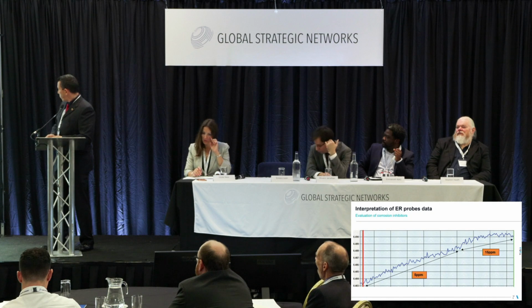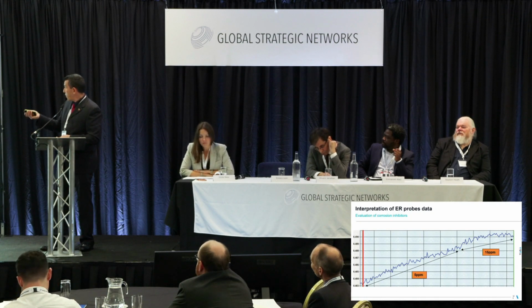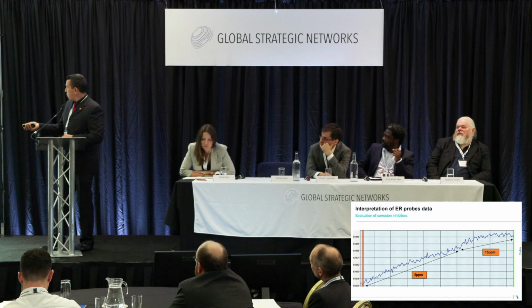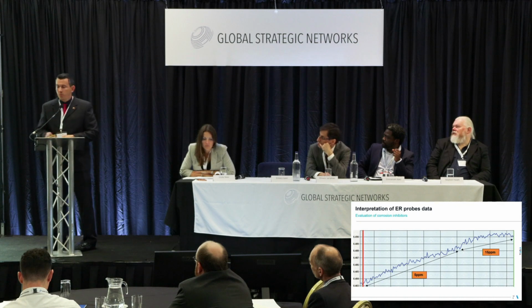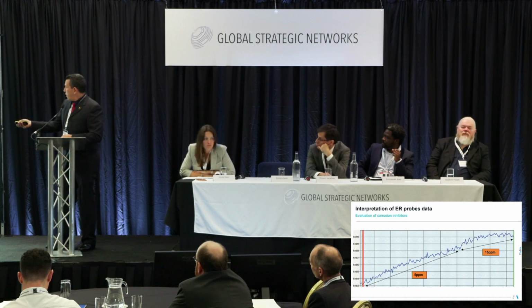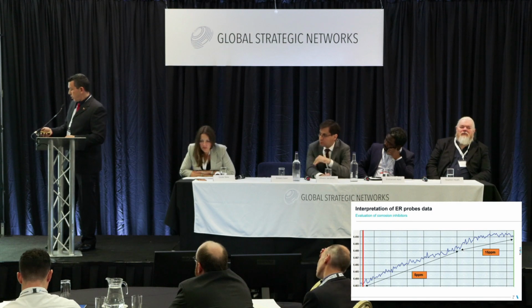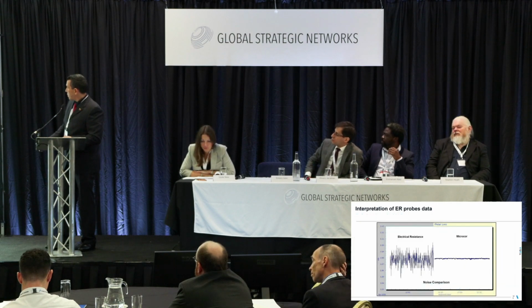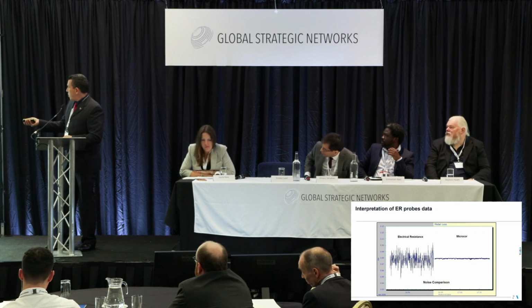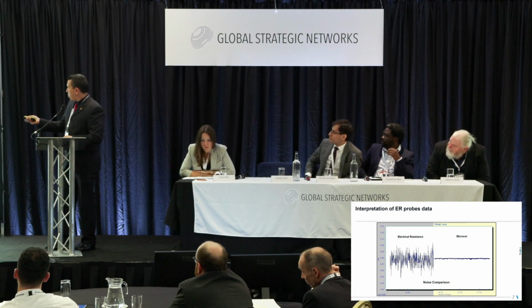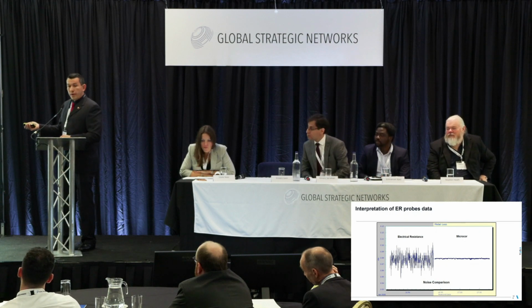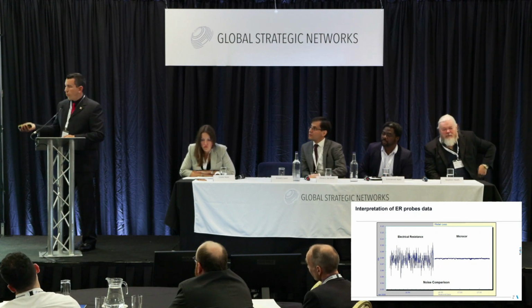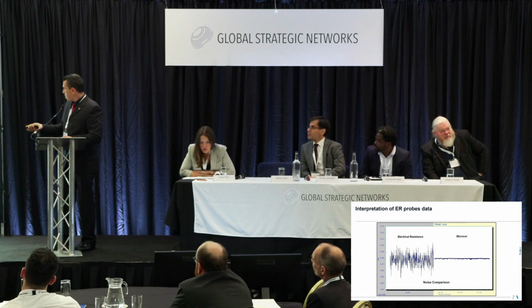This is an example of how we can interpret the corrosion probes, how to use the corrosion probes to optimize inhibitor injection. Here we can say, okay, we were injecting 5 ppm, corrosion rate was high. Then we increased the dosification to 15 ppm, and corrosion rate went lower. This is another example of how the state-of-the-art probes can get more accurate information quicker with less electrical noise.